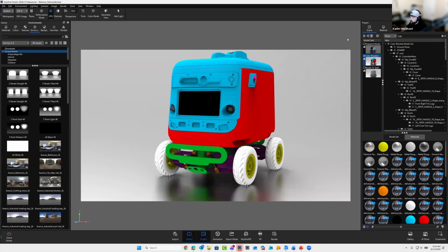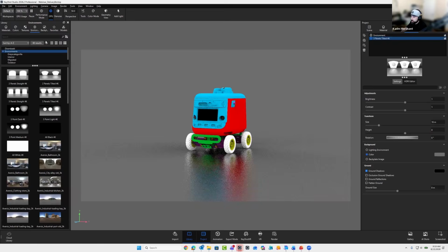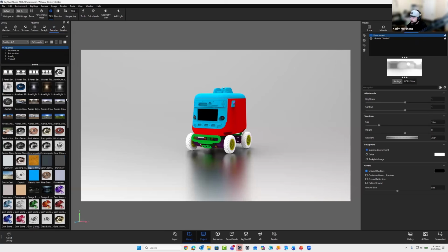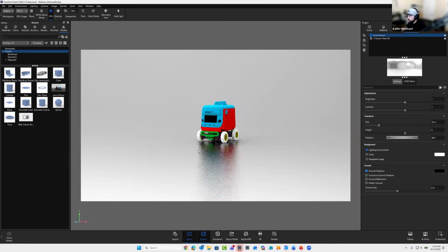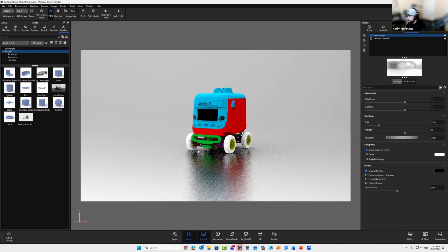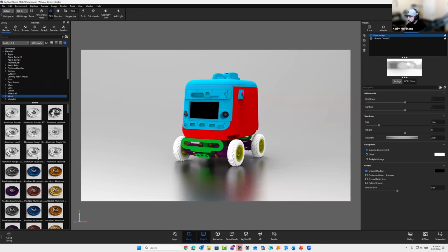And aside from that, you can also import all kinds of different assets. You can import your HDRIs or materials. We have backplates for backgrounds. If you need a quick background, you can save your favorites so you can easily access them. And then we also have some native geometry in KeyShot. You can ignore the Lamborghini, the lawnmower, and the radio here. Those are things I've imported. But all this blue CAD data, it's really useful because you can use it as backdrops. You can build podiums. You can use it to mask lights. I've even built rooms using them so that I could do interiors. So it's very useful to have these on hand and just be able to scale them and apply materials as well. But let's jump back over to materials since that's what we're talking about.